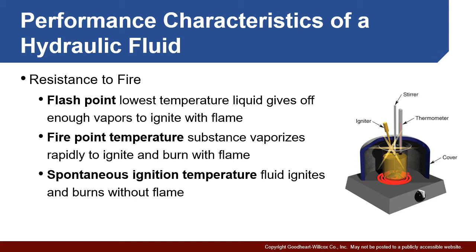On the other hand, if you continue to raise the temperature, eventually you're going to get to the fire point. The fire point in this case is if it's exposed to an open flame, it will not only ignite the vapors, but it will actually ignite the liquid as well, and it will continue to burn. So flash point is the lower temperature, fire point higher temperature, and eventually we'll reach the spontaneous ignition temperature.